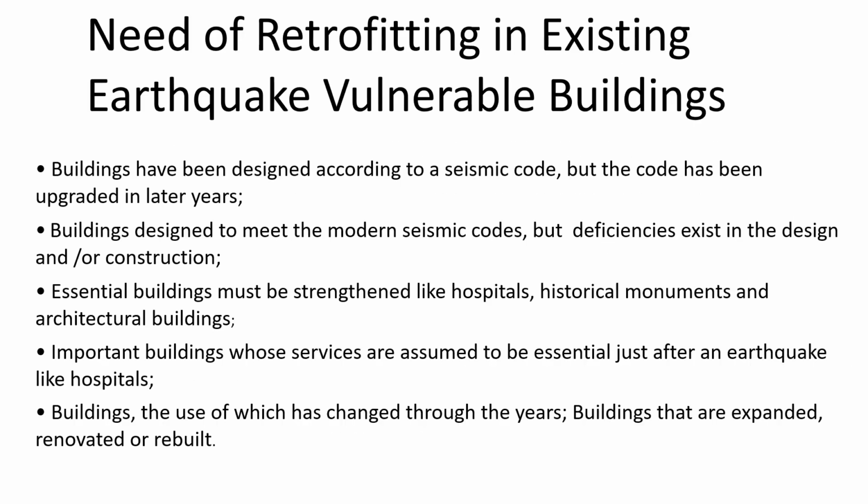Need of retrofitting in existing earthquake vulnerable buildings. Buildings have been designed according to seismic code, but the code has been upgraded in later years. Buildings designed to meet the modern seismic code, but deficiencies exist in the design and/or construction.